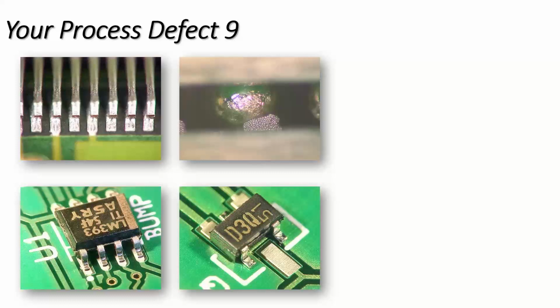But as components and failures get smaller and smaller and smaller, using traditional microsectioning techniques is difficult, because with very, very small joints and surfaces, you create more damage sometimes with microsectioning.